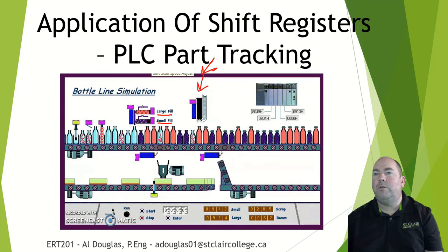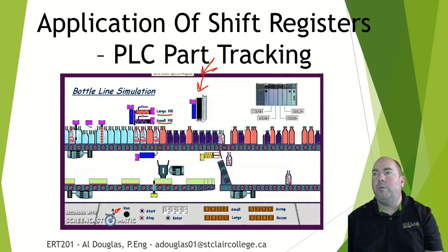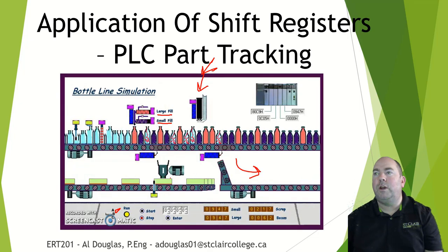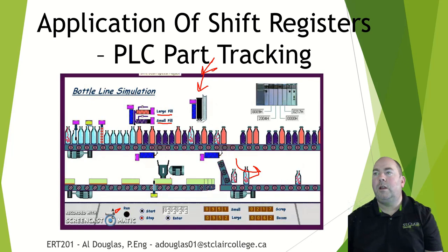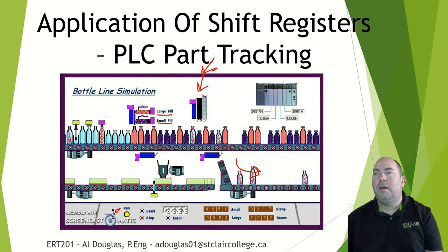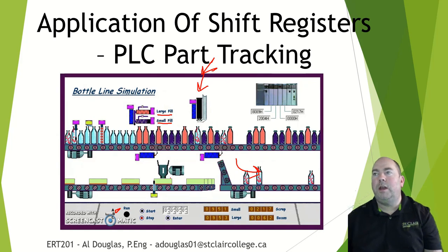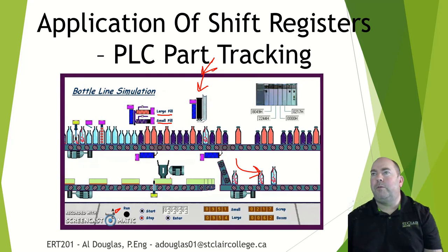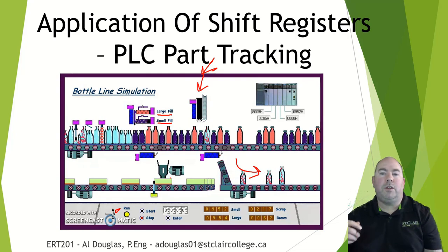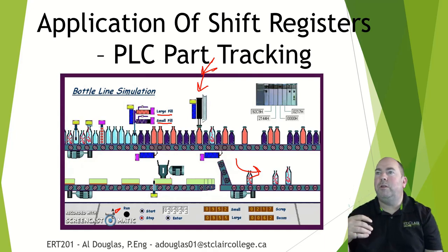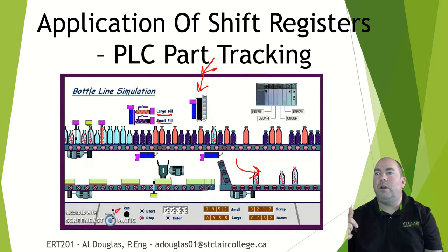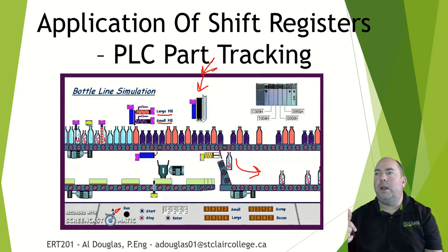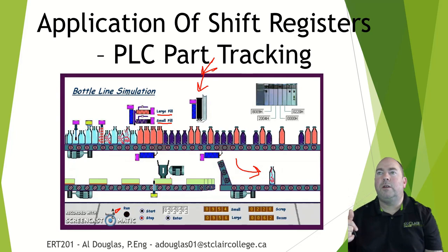Now I switched modes. I think this is mode B down here. Now we're putting the broken bottles down here instead, so this chute opens up and drops the brokens down there. This is all being done through PLC logic, but it's a bit shift left, I think, or bit shift right PLC command that is essentially the same fundamentals as what we were doing with these shift registers. So it needs a data signal, it needs a clock signal, and then that's basically the way that it operates.